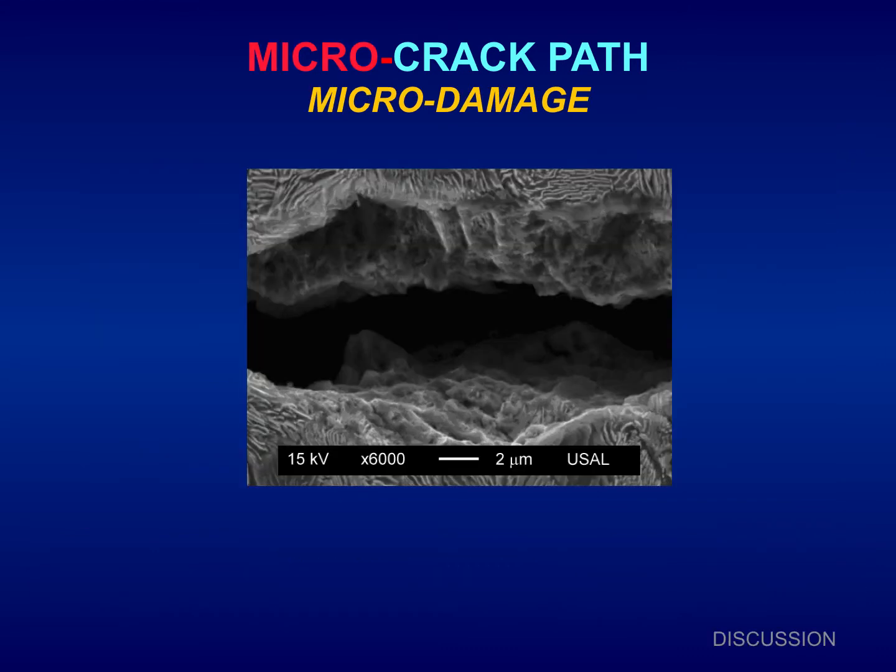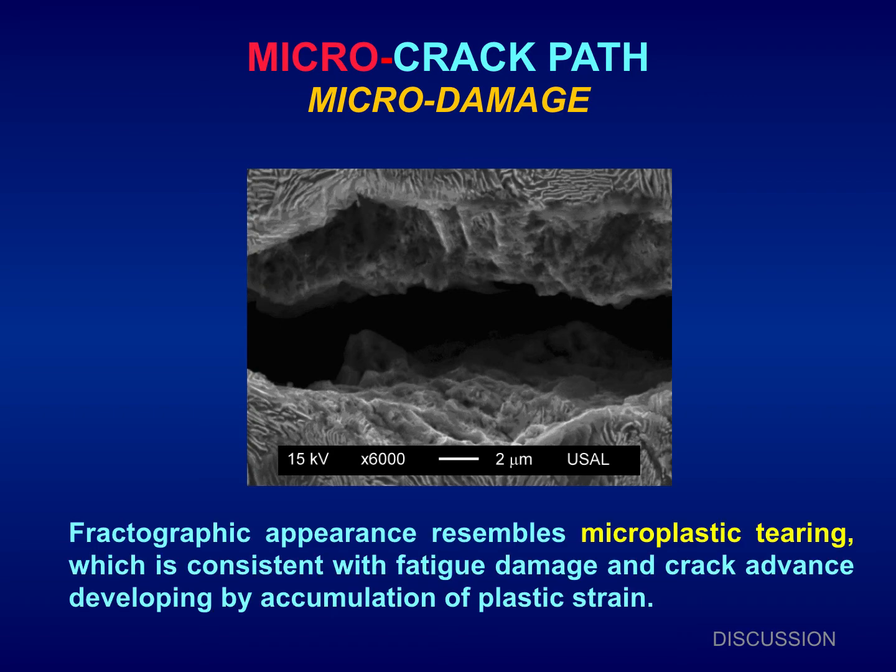Microcrack path resembles microdamage. The fractographic appearance resembles microplastic tearing, which is consistent with fatigue damage and crack advance developing by accumulation of plastic strain.